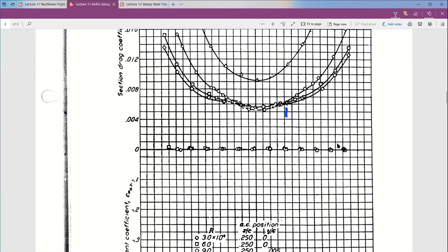And it's the Reynolds number for the whole length, so you put this chord in here. So you guys calculate this. What do we need to know? We know the velocity, we know the chord. We need the density and mu, right? So we need additional information. We need to ask, well, where are we flying?